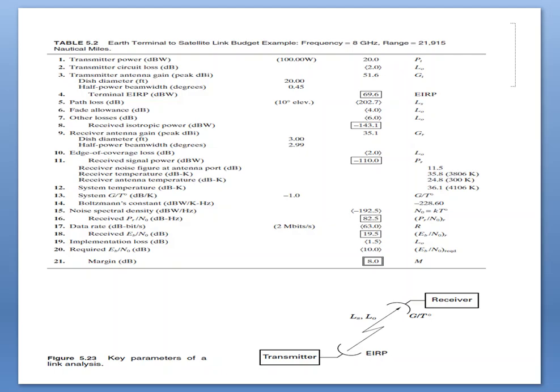By considering all of these, the link budget details are shown in the below figure, consisting of 3 columns of numbers. Only the middle column represents the link budget. The other columns, consisting of ancillary information such as antenna beam width, are computations to support the main tabulations. Losses are bracketed in the visual bookkeeping way. If a value is not bracketed, it represents a gain. The subtotals are shown enclosed in a box.